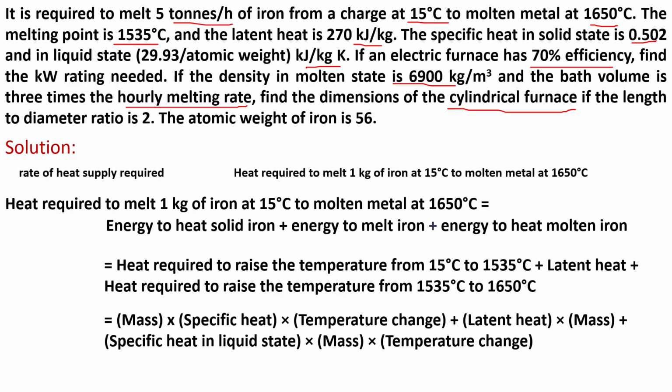Similarly, we calculate the latent heat, and for the liquid up to 1650, mass into specific heat into temperature change. So it is specific heat in solid state into mass into temperature change, plus latent heat into mass for the solid to liquid phase, plus specific heat in liquid state into mass into temperature change from the melting point to liquid temperature.